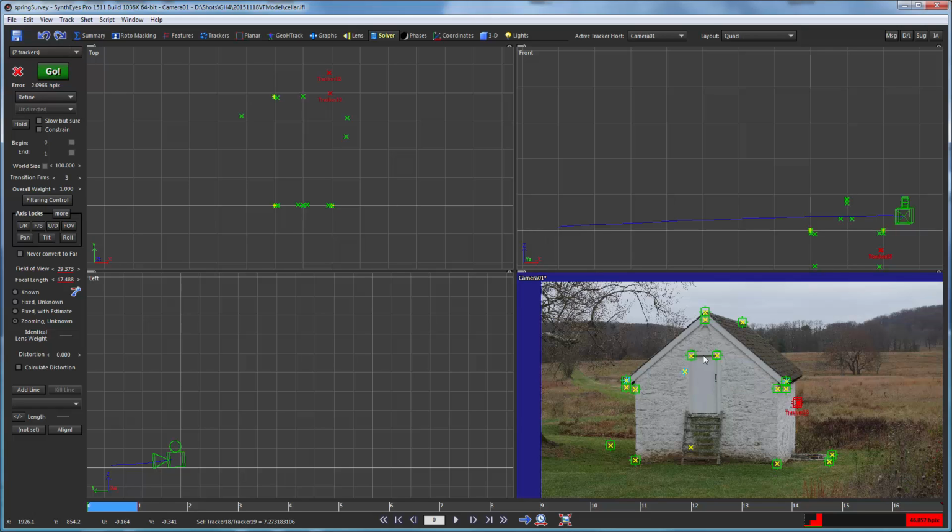If I use just the distance between these 2 points, basically it's going to get multiplied by 4 or 5 to create an error in this direction. So if I'm off by a 1/4 inch, I'm going to be out by 1 inch or more out here. So instead, it's wiser to get a distance that's already the width of the building, for example. And that's the measurement that I have from the original site.